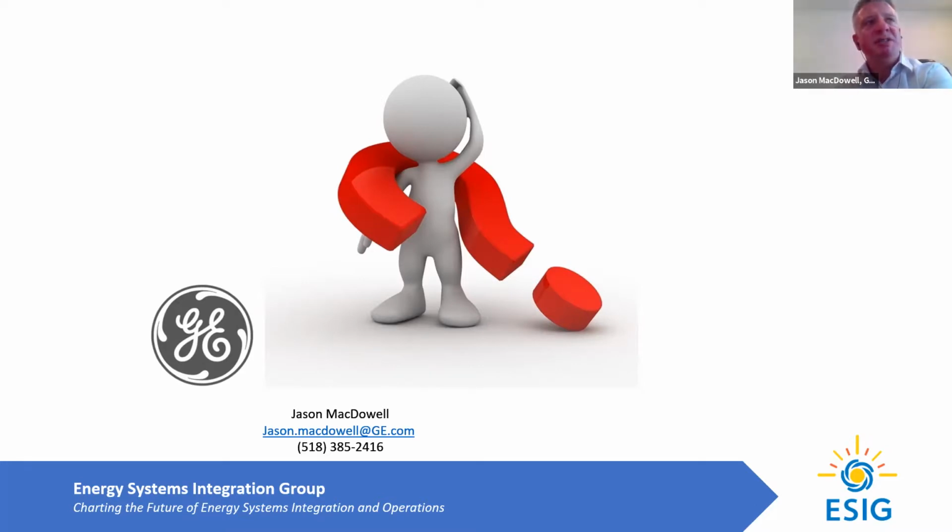Those are the coordination concerns, and IEEE 1547 has gone a long way to try to relieve some of those concerns by allowing voltage regulation where possible and necessary on distribution network connections. So it's getting better, but it's still something to watch out for, to make sure that coordinated control at the distribution level for voltage regulation is done. Again, the capability in the devices for today's technology is largely there, but it's a matter of coordination and having it online and required and deployed in a way that supports the system.